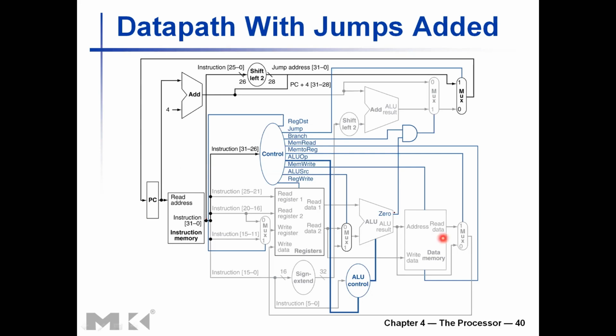The other control signals are mostly don't care, because we are not using them. Register write is 0. We are not writing the register file, not writing to the memory, not reading from the memory. You have to pay careful attention to these write control signals, or otherwise you may be corrupting data in the register file or the data memory by writing garbage values into random addresses.